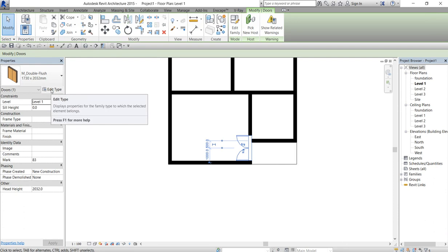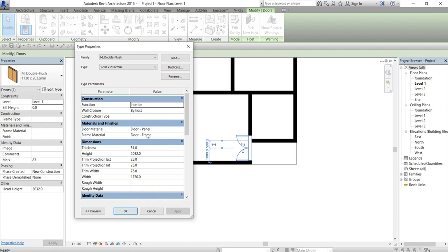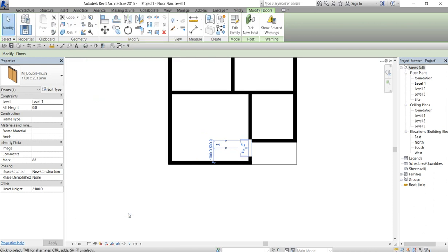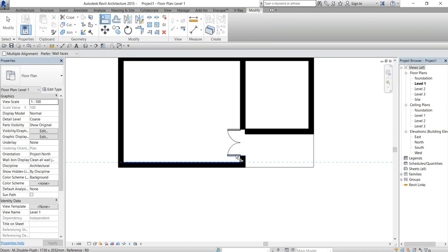Now go to the properties bar and modify the door. Here you reduce the width of the size. That's the most important first. So let's say 120 millimeter. Then this one normal height, 2100. And say okay. You see how to reduce. So align it to the wall.